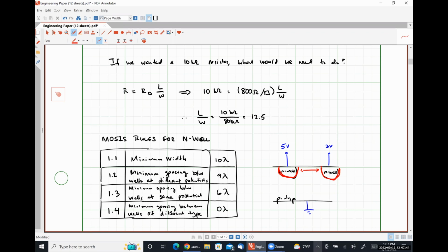In this class, we are going to look at what's called a beta multiplier circuit, which gets band gap voltage reference circuit like behavior, but can be created without utilizing parasitic bipolar junction transistors. Okay.